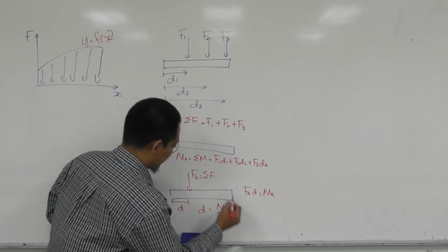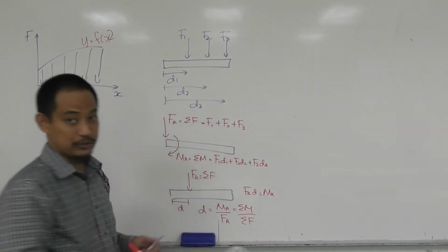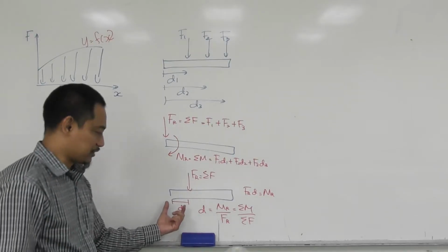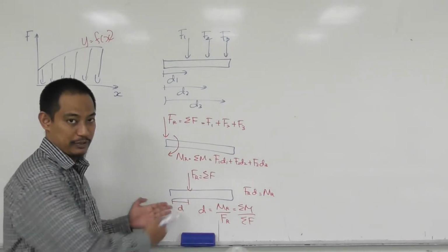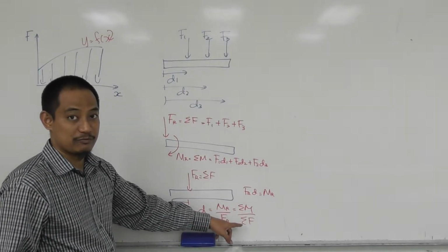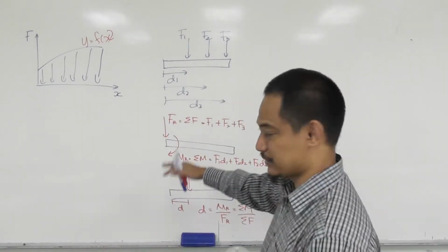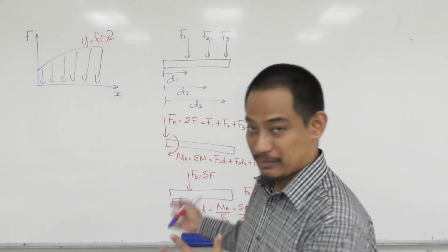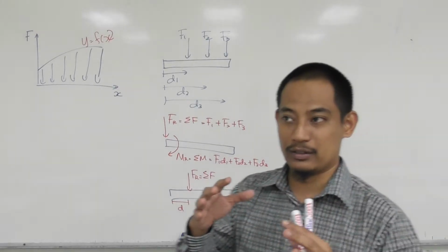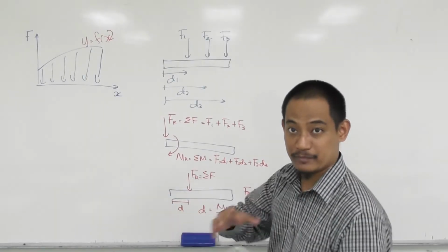And Mr we know is basically the summation of moments, Fr is the summation of all the forces, right? So essentially we can calculate this location, or this distance in 2D, as the summation of moment divided by the summation of forces. So the concept is there, right? If it's 2D, it has x and y components; if it's in 3D, the concept is still the same, right? So this position is what will cause the moment to be equal to the resultant of moment, right?